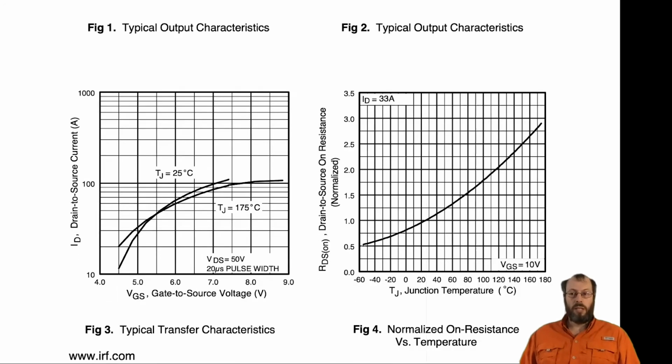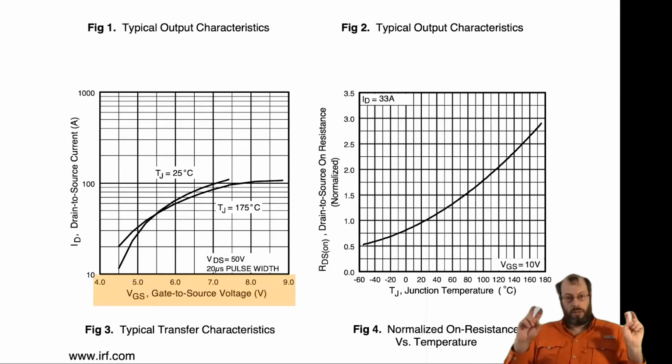Moving on to the next two diagrams in the datasheet tells us on the left-hand side about the control characteristics of the device, starting with the gate source voltage, the controlling parameter of our potentiometer in the simplified case, on the x-axis, and that one also starting at the threshold voltage maximum of 4 volts.